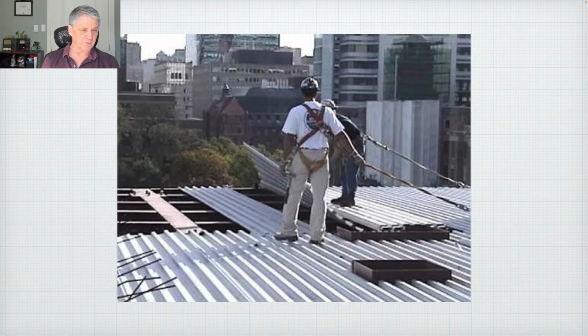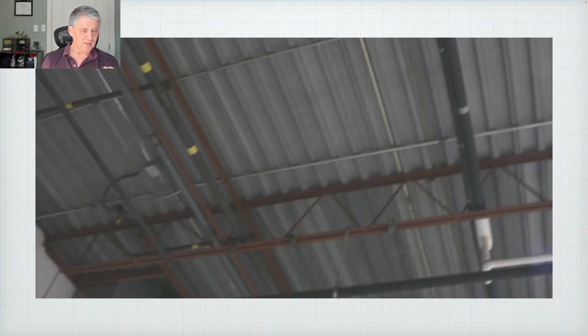So this is the roof. Now, this is the underside of the roof, and we often will secure our pipes to the roof. And in the fashion here, this is not uncommon. We see this all the time. We have a junction box. We have a piece of, this is either a TECK, it looks like probably a TECK with it stripped back as such, and this is going up to a rooftop unit. And we have raceways on the surface.